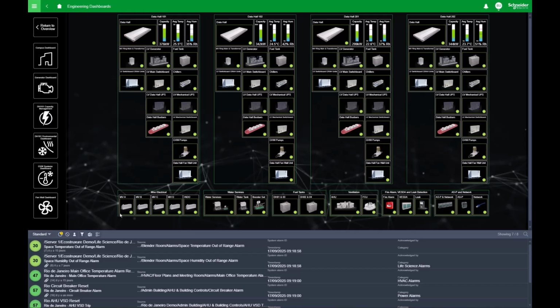Another example is a chiller failure. It's of course very critical. You'll still get your alarms indicating that there is a problem with one of your chillers in the data center. However, if your data center is built with an N+2 redundancy, then operations are still going to continue relatively smoothly. So in that case, this particular dashboard will not show any changes because the system overall is still functioning as designed and you have continuity in your service.